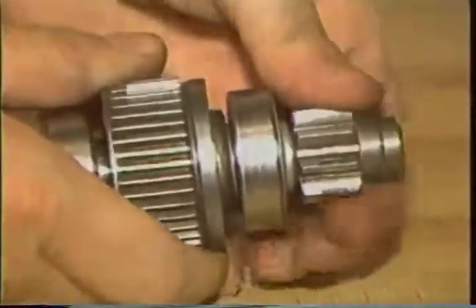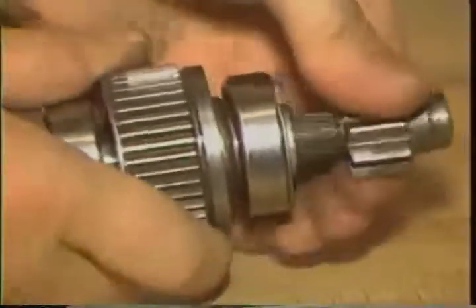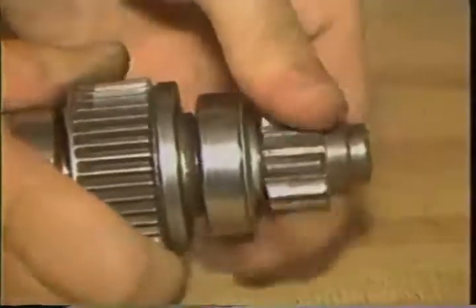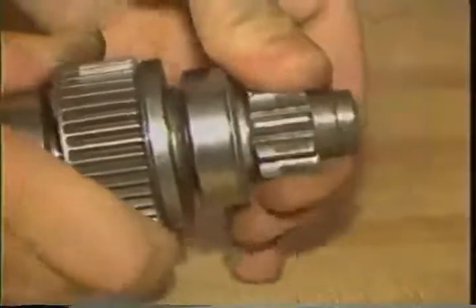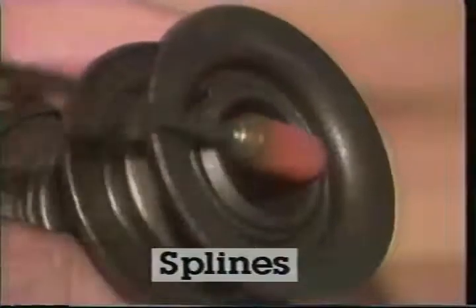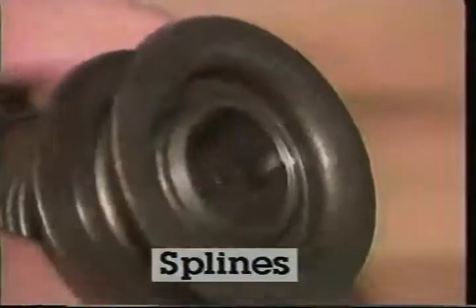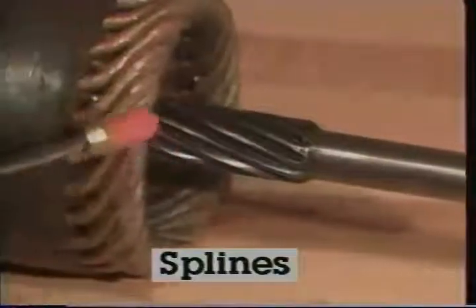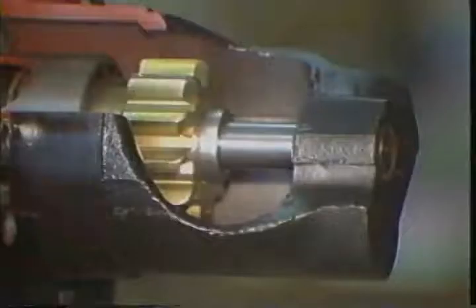The pinion gear must also be splined to its shaft so that it is free to slide outward and into engagement. As you will learn in the next video, the starter clutch assembly and pinion are the most common parts to fail in service because of the severe loading. Splines inside the pinion assembly mesh with the splines machined onto the armature shaft. The spiral splines help throw the pinion gear outward when the starting motor is energized.